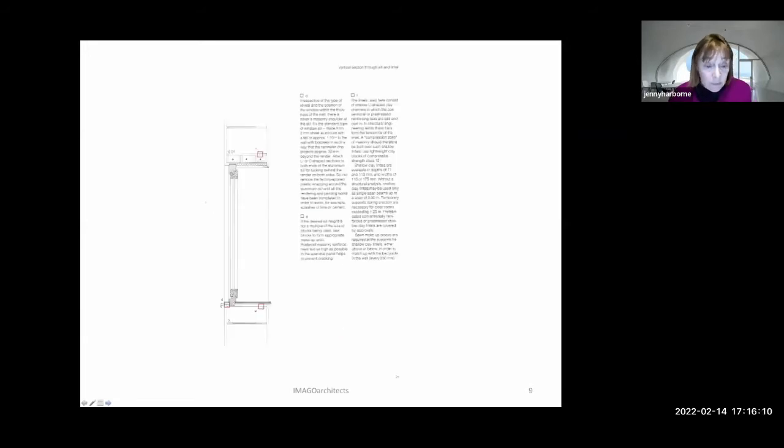And here is a detail through a window with one of the proprietary lintel blocks. This will be like a clay block, but you'll have a series of them going across the opening, and we just fill them with concrete and put some rebars in, and it's just so simple. They're just part of the wall. They have different forms of these. Sometimes there's a cellular part to them, but if not, you'll probably need to put some insulation in there to keep the continuity.